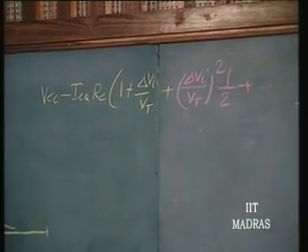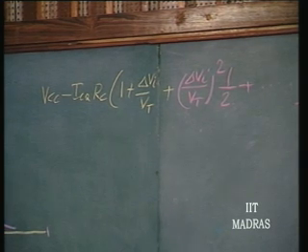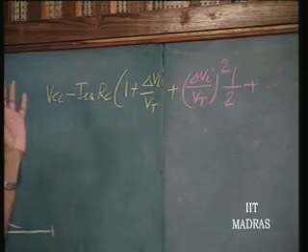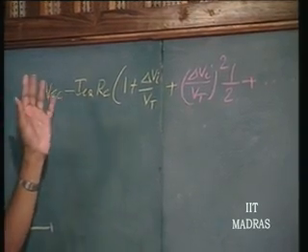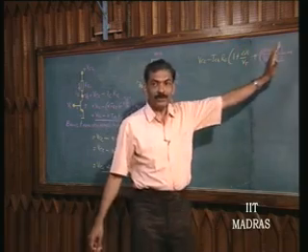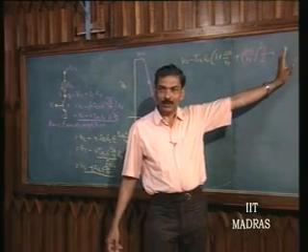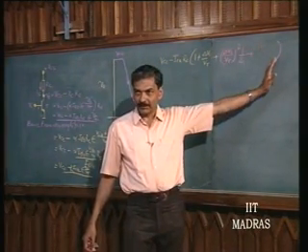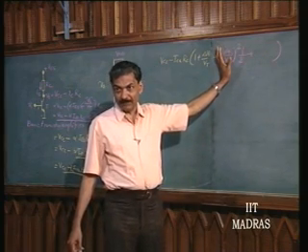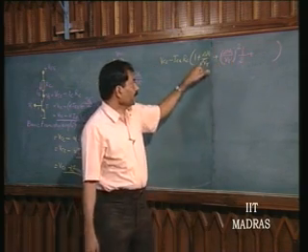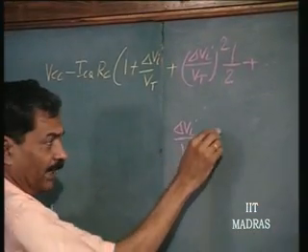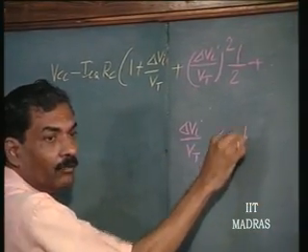So, in an amplifier which is supposed to be linear, delta Vi when it varies, okay, output should vary according to delta Vi. So, that means all the other terms should become very small. These are the non-linear terms. So, what is the condition for this to be a linear amplifier? We can see that delta Vi by Vt has to be much less than 1.